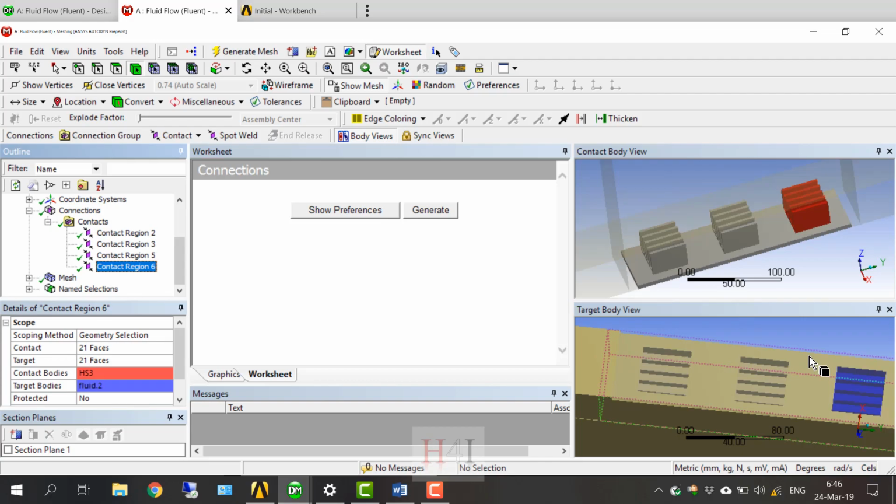Fluent will automatically take this contact region and create the interface for you. You will not do anything on your part. Okay, but sometimes the contact region has some issues. Instead of creating 4 contact regions, you may find 6, 5, or another illogical number. It divides one region into 2 contacts. This sometimes causes problems in Fluent.